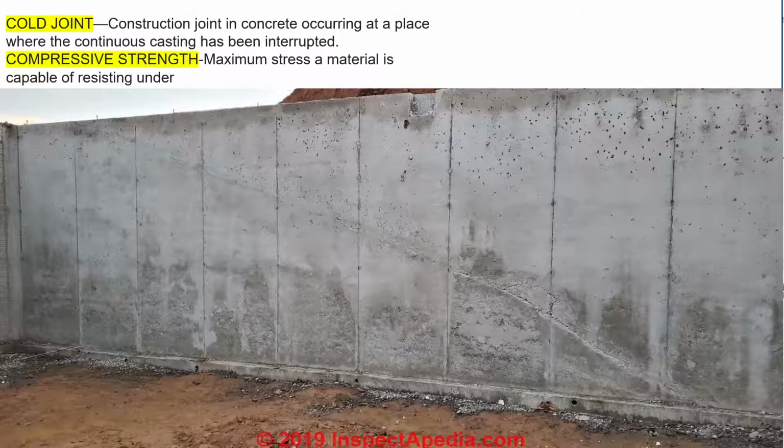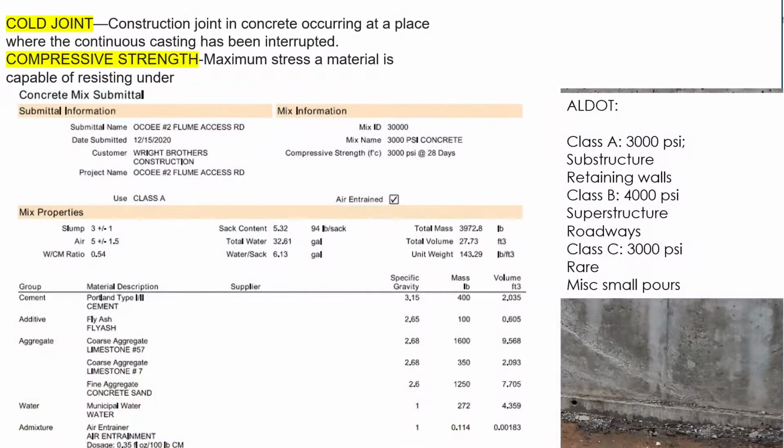So compressive strength is the maximum stress a material is capable of resisting. This is a typical concrete mix design submitted by a concrete supplier. Right here we're talking about ALDOT. ALDOT classifies their concrete into classes, class A, B, and C. All states do the same, but sometimes their 4,000 psi might be a class D or a double A, double B. You just have to pay attention to your specs. But here in ALDOT, it's class A, B, and C.